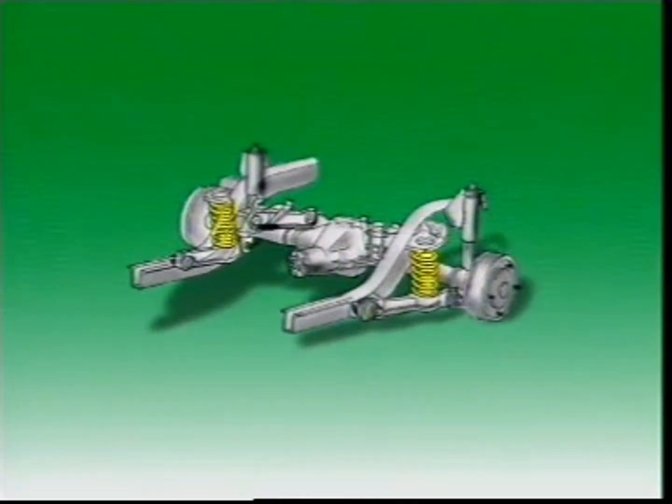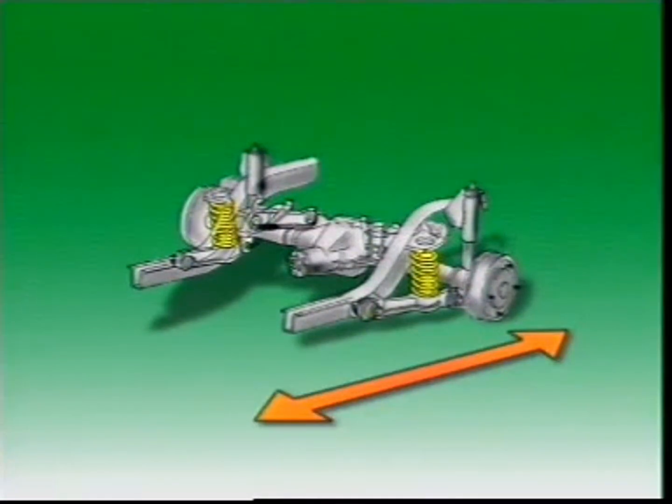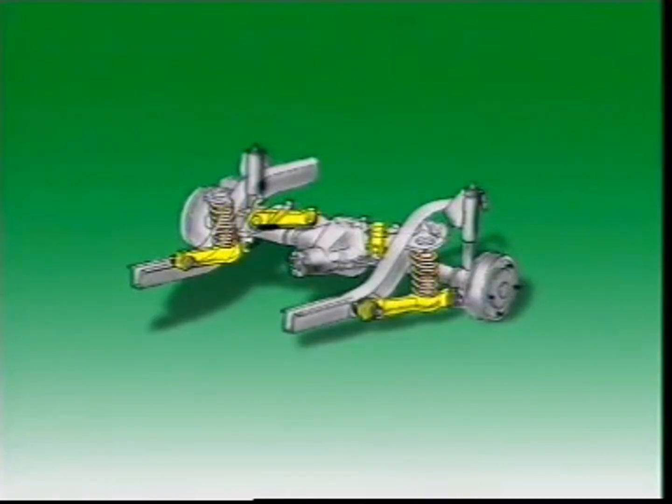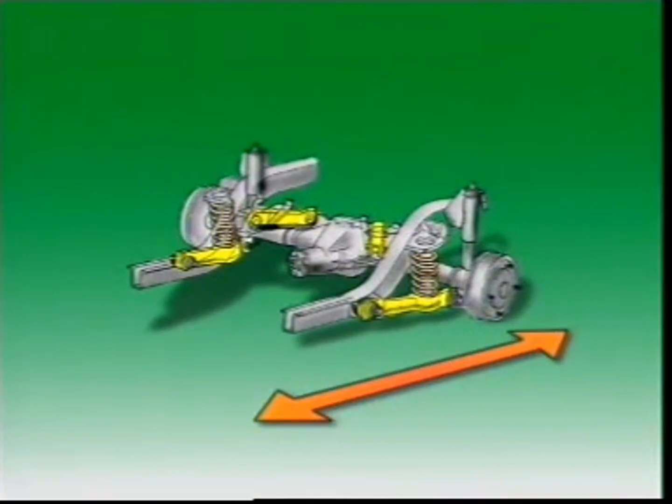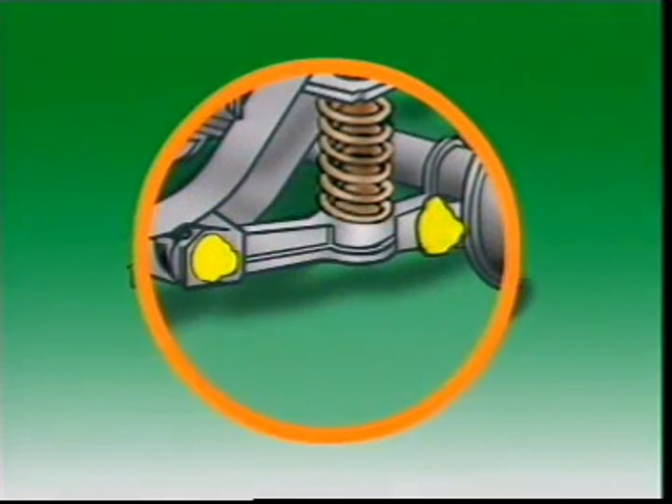This rear-wheel drive vehicle has coil springs in the rear suspension. Therefore, special provision must be made to locate the axle laterally and longitudinally. Trailing arms or control rods are used to position the axle longitudinally. They have flexible rubber mountings at each end where they locate on the axle housing and on the chassis frame.